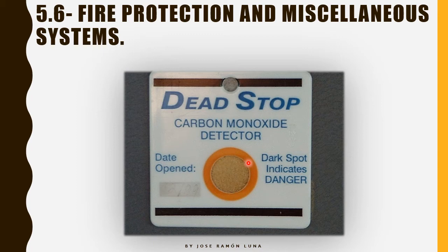So if you ever turn your head towards this and it looks black or dark, it means that you have a carbon monoxide leak and you should act appropriately. Well, act appropriately against carbon monoxide. Opening windows, opening vents, seeing if something's wrong with the engine and trying to land as soon as possible.